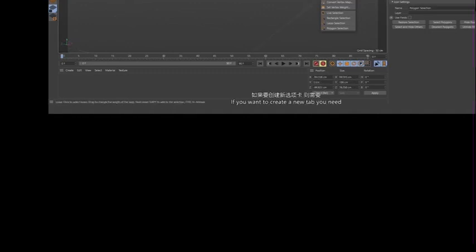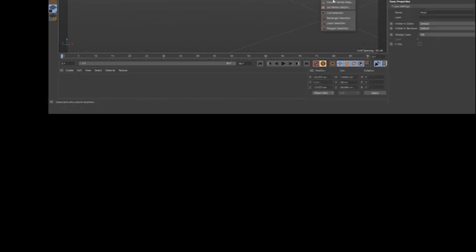If you want to create a new tag, you need to select New Polygons. Deselect the old selection tag and apply Set Selection. Otherwise, the selected tag will be overwritten. These are the tools available for working with polygons. Right now, it is of course difficult to figure out which tool to select, but you will understand this as you gain more experience. So we will cement our knowledge in practice.